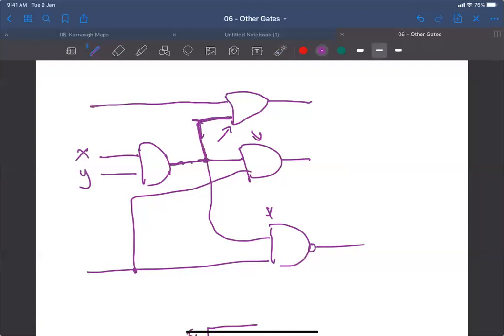The result is going to be a malfunction in the circuit. So the solution, in order to make the output strong enough to drive the other gates and give it driving capability, is to include a buffer. The symbol for the buffer is similar to the inverter without the bubble. The inverter is represented by this symbol, notice the bubble here.